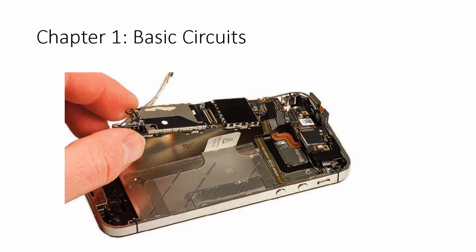So it's important for them to understand what different components look like, size factors, form factors. So if a mechanical engineer doesn't understand an inductor and the specific form factor that it has, it's much harder to package that. And you might put that into a space where then all of a sudden you need more material around the side. More material costs a lot more money when you're doing hundreds of thousands, if not millions of different devices, different iPhones, or whatever the electronics you're trying to do are.